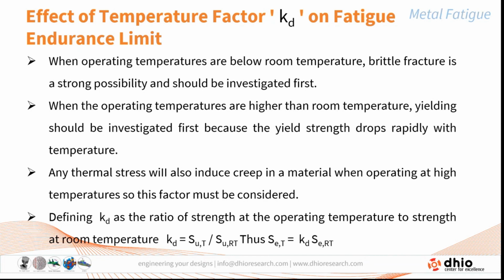So any thermal stress will also induce creep in the material when the operating temperature is high, so these factors have to be taken into account. Now, defining the load factor Kd as the ratio of the strength at the operating temperature to the strength at room temperature, Kd is equal to SUT divided by SURT. Thus, SCT, the endurance stress at the temperature, is Kd times the endurance limit at room temperature.